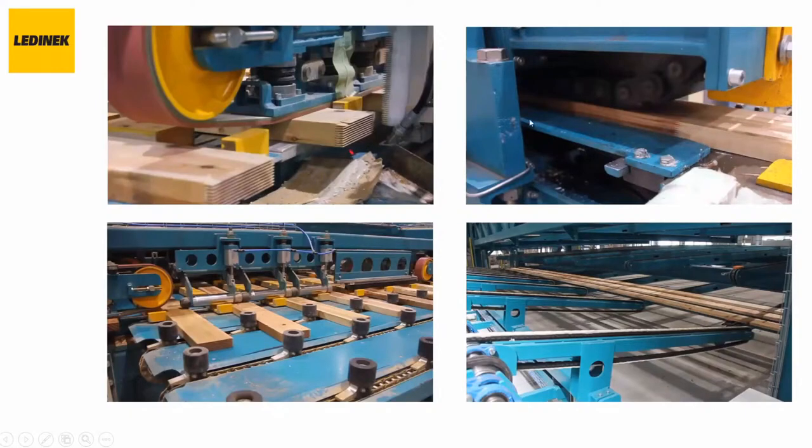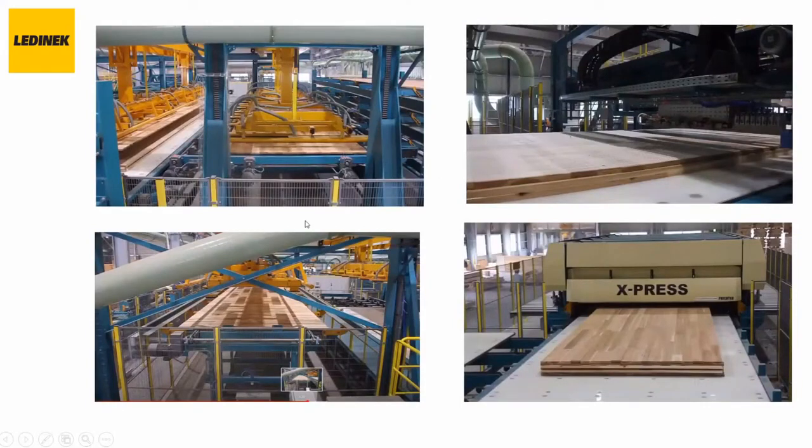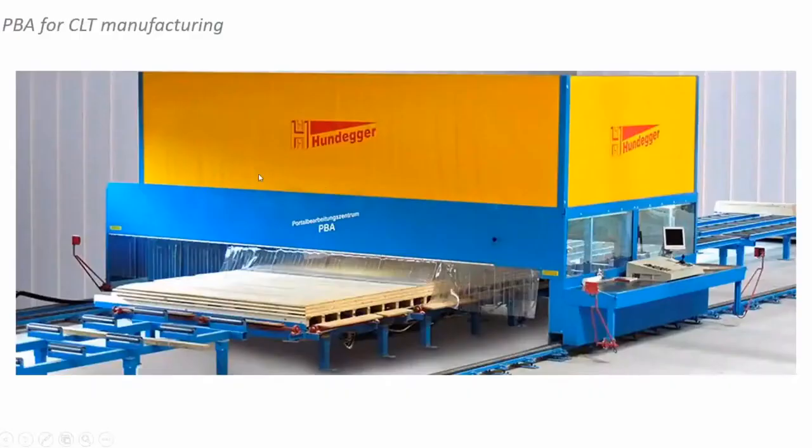They're cut again, placed side by side, and oriented in X and Y direction. Glue is applied, they're pressed, and then you have a CLT plate. And then you have a few subtractive fabrication processes, like the standard for many companies that have worked with them.